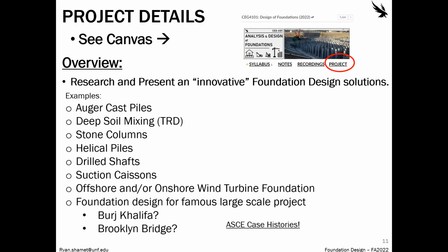This is also used a lot in areas where there is a lot of groundwater movement, and you can't block those. Helical piles, those are good for tension support as well. Drilled shafts, suction casings, offshore and onshore wind turbine foundations. These are crazy. In Norway, they do a lot of cool stuff. You can look up there for these massive structures, like the largest geotechnical engineering structures. And you can also do foundation designs for famous large-scale projects.